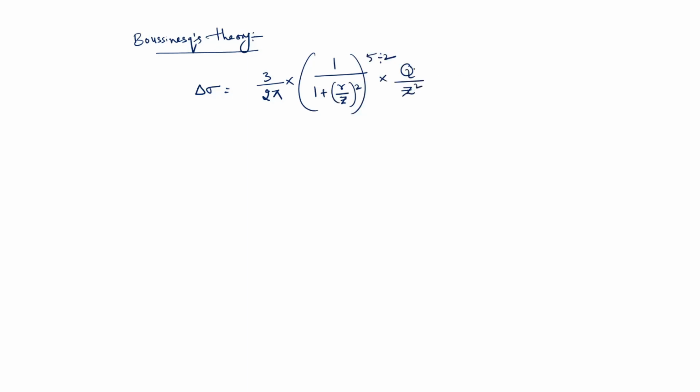Here Q is the load, and z is the depth at which you want to find the increment in stress. Let us say this is the load, this is the line of application of the load. Suppose at this point you want to calculate the increment.